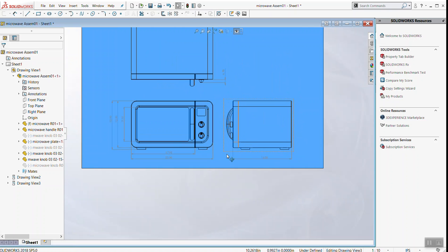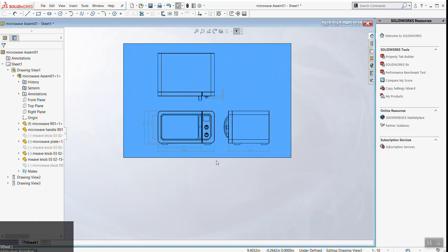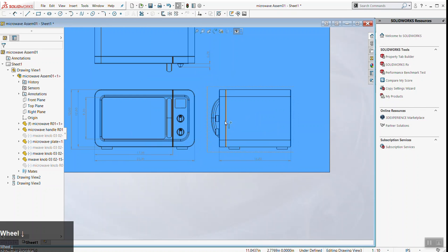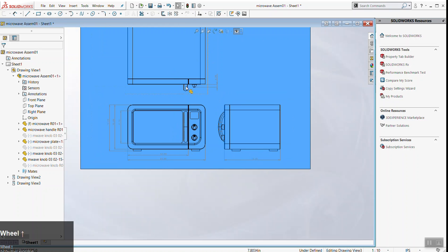Okay, as long as you have this and print it out, that is one of your requirements for project 2. Again, as long as you have the overall dimensions, so overall width, overall height, overall depth. For what it's worth, if I got this, I would mark it wrong because it's missing the depth of the handle here. It's not the overall depth, it's just the depth of the microwave. If you followed the first 3 things I did, you're good.